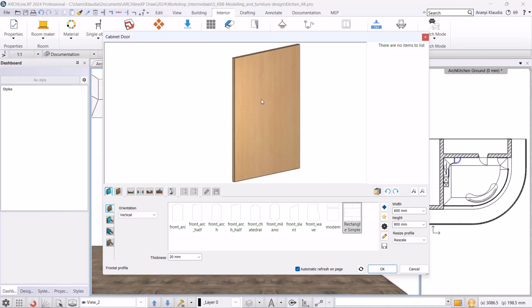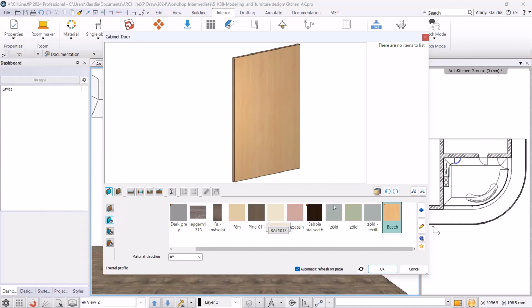We can do different edits. We can create an insert profile, a glass front with the hole command, and we can add or subtract a profile. To create the hidden handle, we will use the subtract profile and add profile commands. We will subtract a profile of 40 mm from the front and then use the add profile tool to make the hidden handle. Let's look at the process. First, I give the front material, which will be old ash tree.